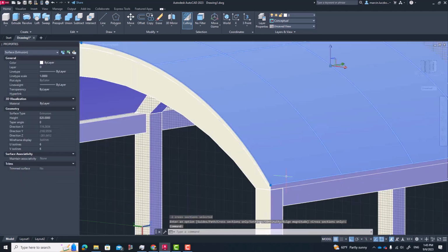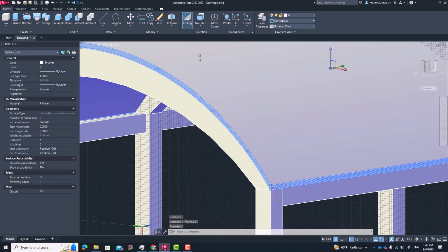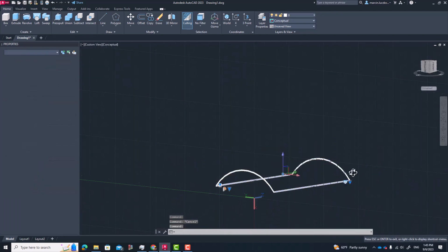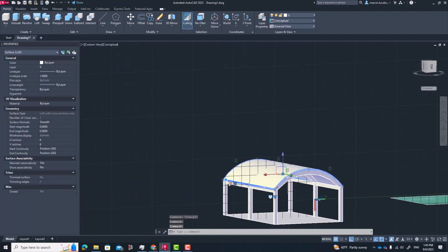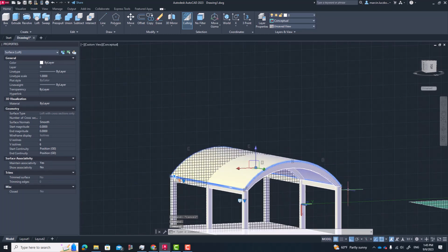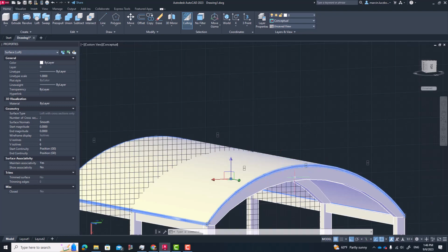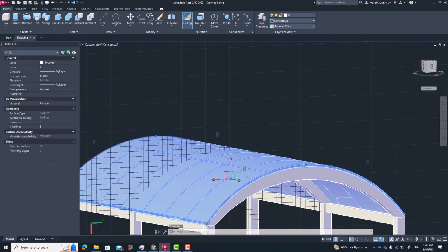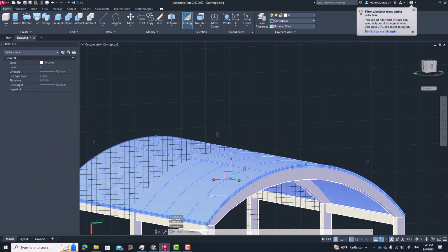So as you can see right now, we should have also the loft here, but this is a surface which is generally its border or its boundary on the right and left side. It's not involving the top and the bottom side of it. If I manually connect it, so now I have like 3 elements, one border which is going around, one top layer and a bottom layer. Now I can try to union them.